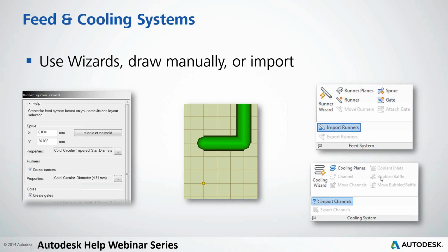Now, if you do that for the feed system, you're going to have to manually create the gate and the sprue after importing those. This is just the way that Moldflow Adviser imports. It's not able to capture those gates and sprues because of the mold size that you assign to it. So adding them manually afterwards gives you a little control and makes sure it's getting to the correct positions.